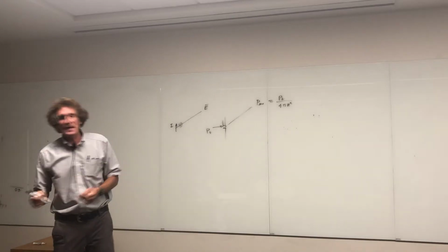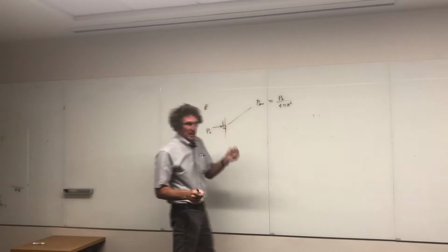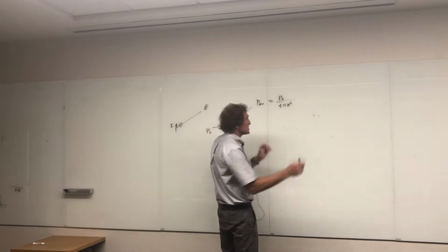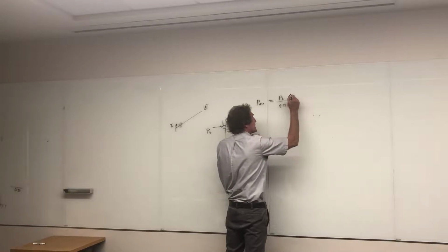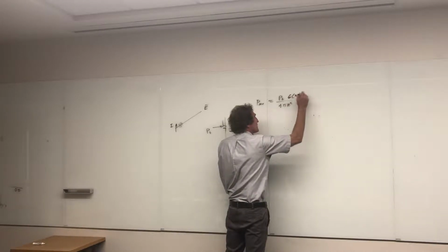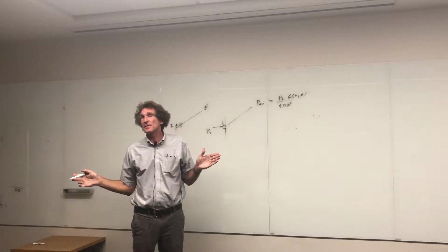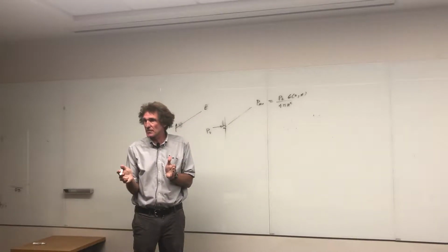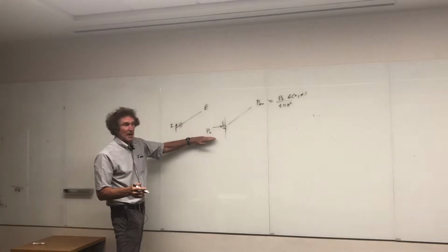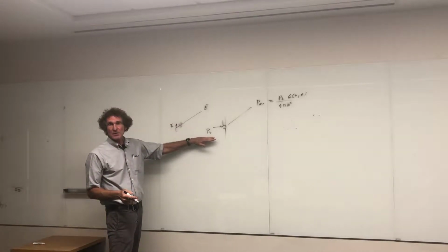The only thing the antenna does is focus the power, right? And the way it focuses is with something called the gain. Gain is a function of angle, theta and phi, not of distance r. So gain is something that focuses power in a certain direction. It doesn't increase the amount of power, just focuses that power in certain directions. Got it, class? That's it.